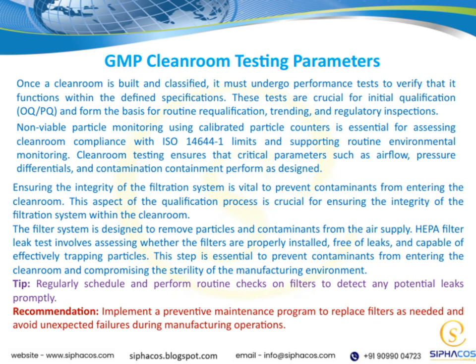Performing this test is essential because any leaks could allow contaminants to bypass the filtration system, posing a risk to the manufacturing environment. A good tip here is to schedule regular checks on your filters. Routine inspections can help detect potential leaks early, before they become serious issues. Additionally, implementing a preventive maintenance program to replace filters as needed can help you avoid unexpected failures during critical manufacturing